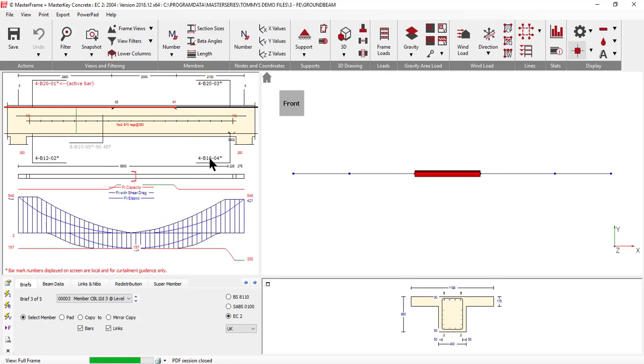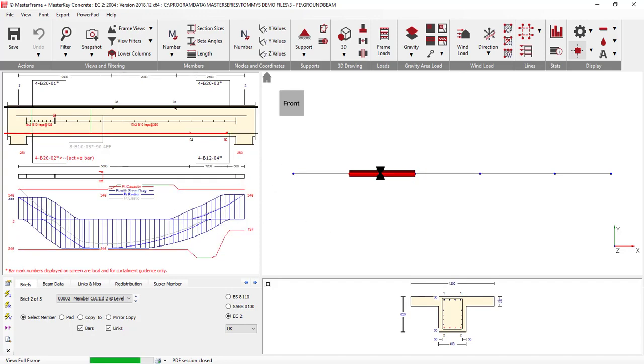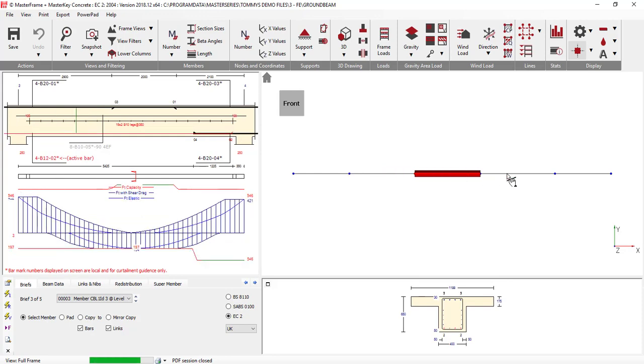So I am getting a little bit here, and I am just going to take this bar and increase it. There we go. There was no real need for anything else, and then just pull that back. So we just drag the bar back. It wasn't requiring a lap because there was no in fact rebar in there that it needed, but we will just ask for one automatically and it then does it for us. So that's how simple it is to do the design of a simple beam.